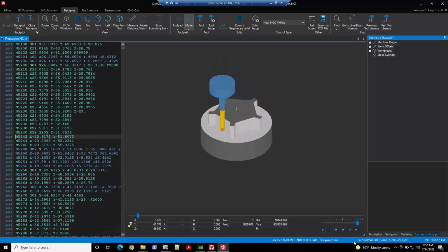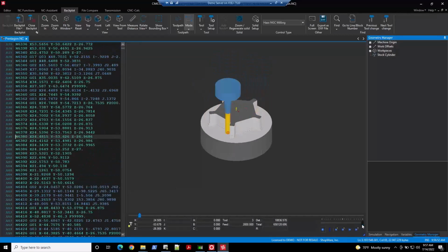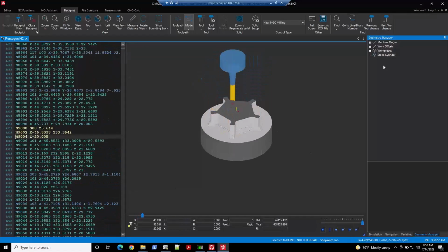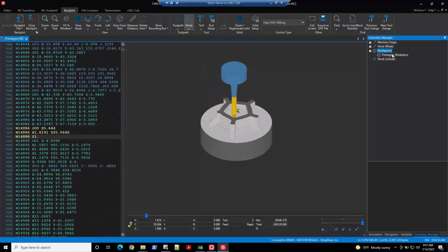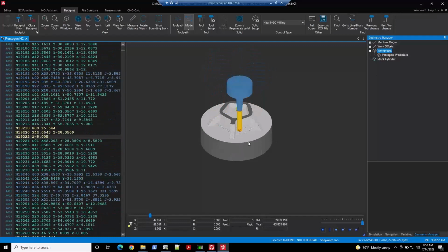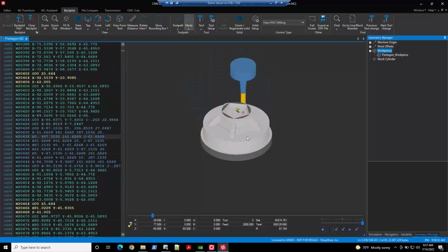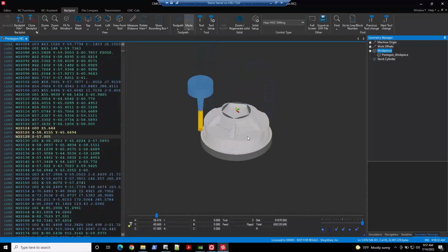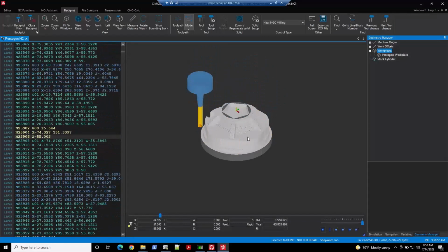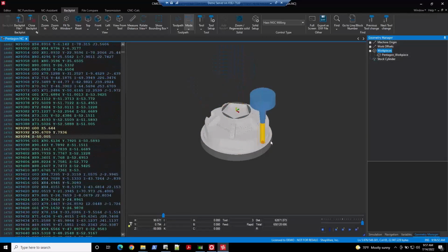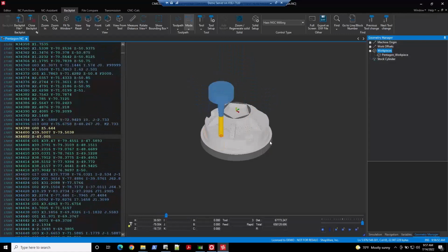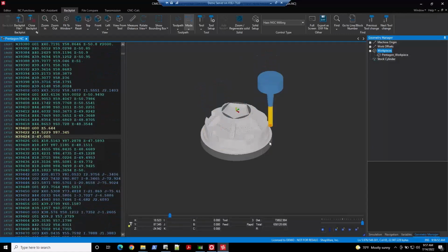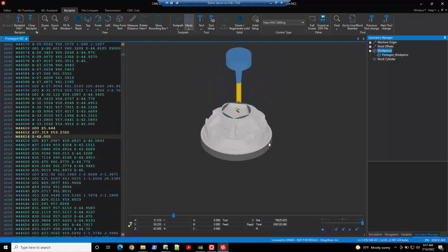But what this is going to do is keep taking off material until we're closer to our workpiece that we defined. So you'll be able to see the 5-axis motion once it's done with its second roughing pass here. This is mainly on an OptiRough section, it looks like, or a typical toolpath like that.